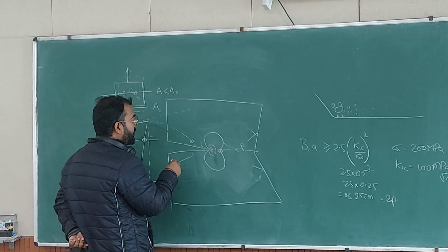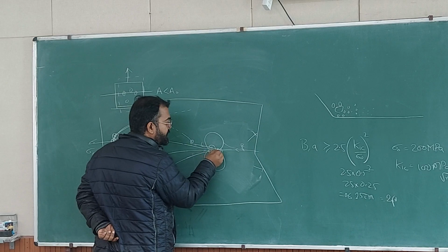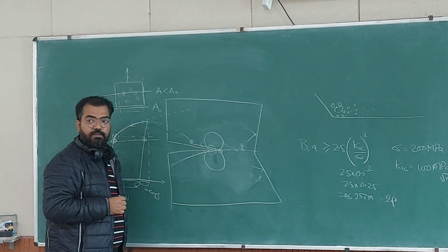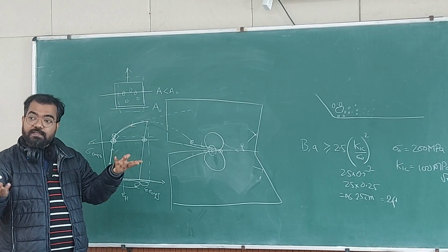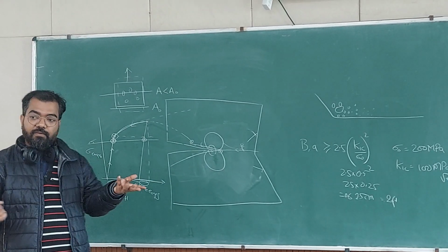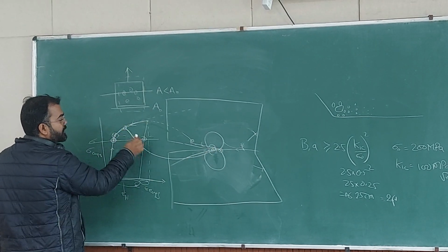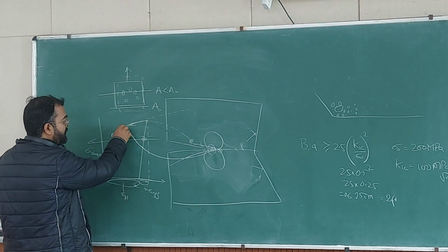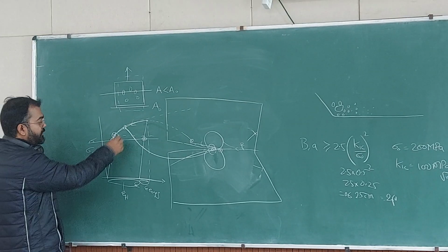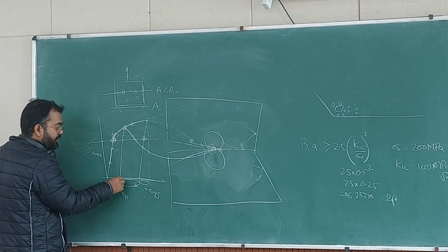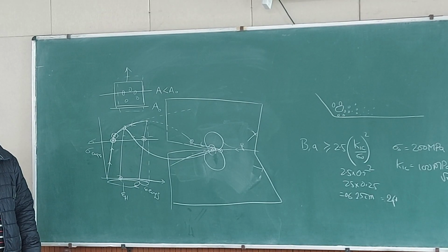The other thing which you are probably talking about is that when a crack opens up, then you had some material points which were connected, and when the crack opens up, these material points are now stress free. So there is an unloading. Okay, wherever these stress points were, so this point probably was here, the crack has opened up and this has now gone to this value. So unloading has happened. Okay, so if it is elastic, it will go there. If it is plastic, it will go here. Okay, this is an unloading. This is a true unloading.